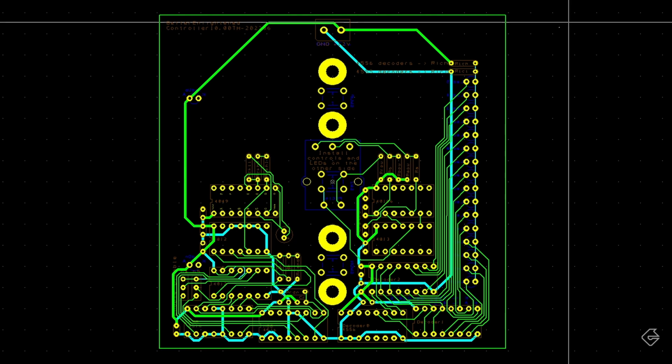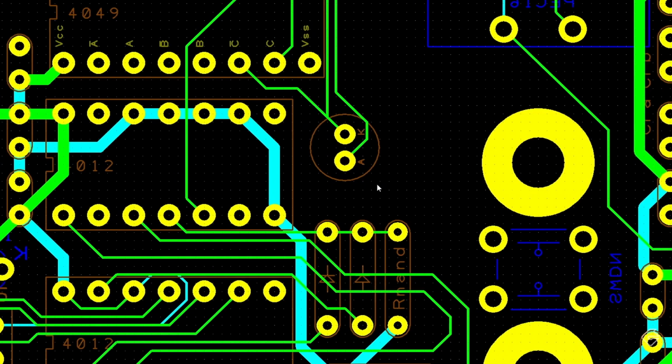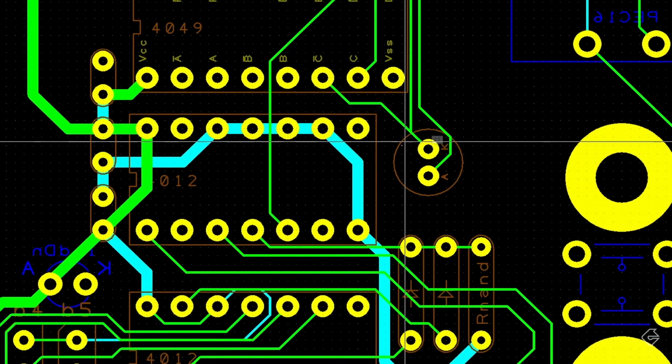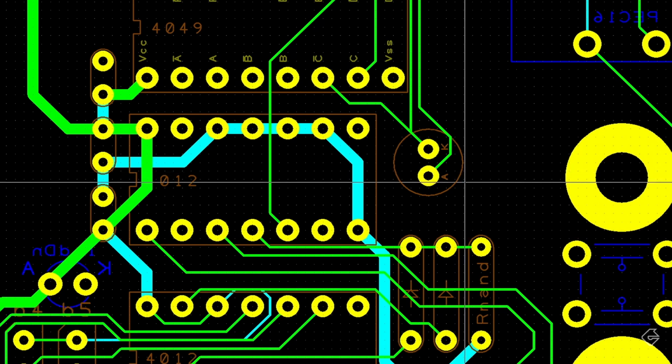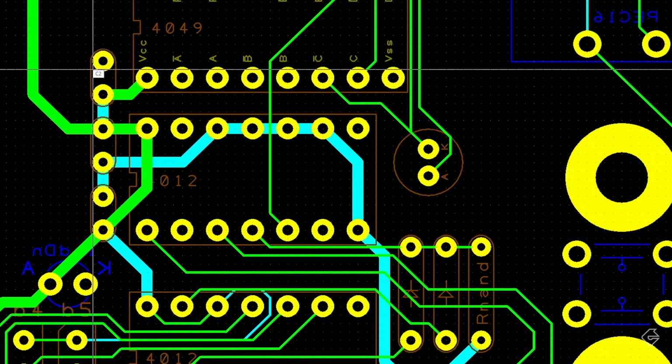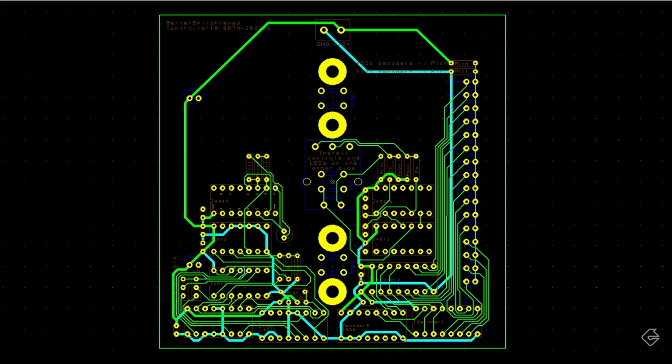So on the PCB, you can clearly see where the capacitor is laid out. Let me zoom in a little bit. And you can see this little circle over here. This is the footprint for the cylindrical capacitor, the radial capacitor it's often called. The other capacitors that we're using for bypass capacitors look a little different. So that's why the footprint looks a little different. Let's continue moving right to left on our schematic, and we'll add the remaining components in. Let's add in the 2 diodes.